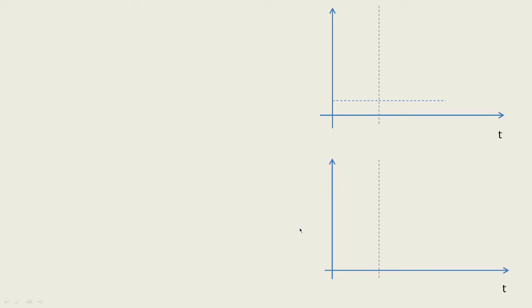So this is how we have obtained the graph for impedance under changing frequencies. Let us understand this graph in detail. What we got is a curve in this fashion, where you have the frequency known as resonant frequency, where the resonance is occurring, and the impedance is equivalent to the R value. This we can treat as the minimum value of impedance that can be obtained for an RLC series circuit applied to AC.